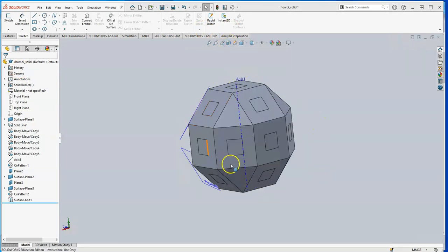The next thing I want to do is create a spherical cutout near the bottom of this to represent the bulb. So where you put in the bulb through the bottom, and that heats up the space. So I'm going to create a spherical cutout of a diameter 60 millimeters. A generic bulb is approximately 100 millimeters high. So the top of the bulb is going to be 100 millimeters off the base of this base here. And then the center of that sphere is going to be 70 millimeters up.